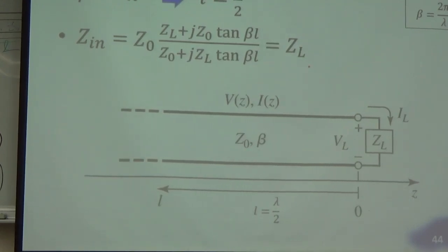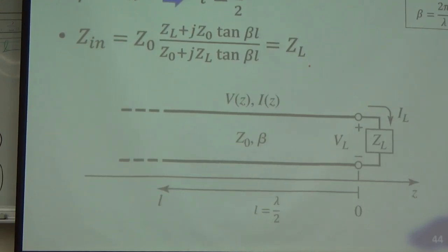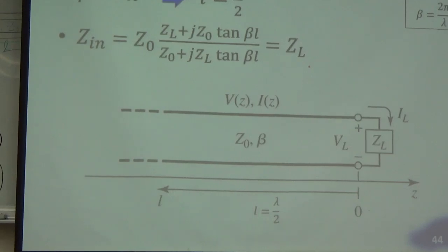It's better than not only 20 dB, not only 30 dB, not 40 dB, it's 100 dB or infinite dB. It's perfect. That never happens in the real world, right? You guys know S11, if you have more than 20 dB, 30 dB, it is a better design, right? If it's totally matched. Okay, for the third case, it is matched.